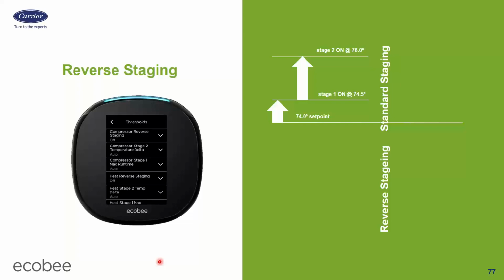Then what normally happens on an Ecobee stat or just about any other stat you've ever used is both stage 1 and 2 continue to run until they both get everything all the way back down to the original set point of 74 degrees. So they both turn off together. Now, reverse staging works a little different.